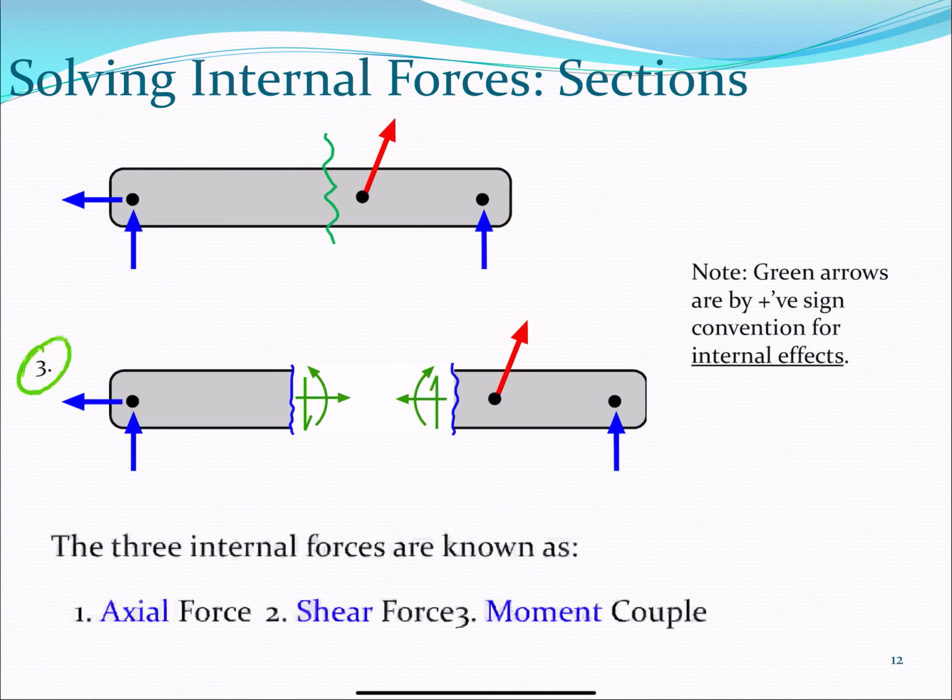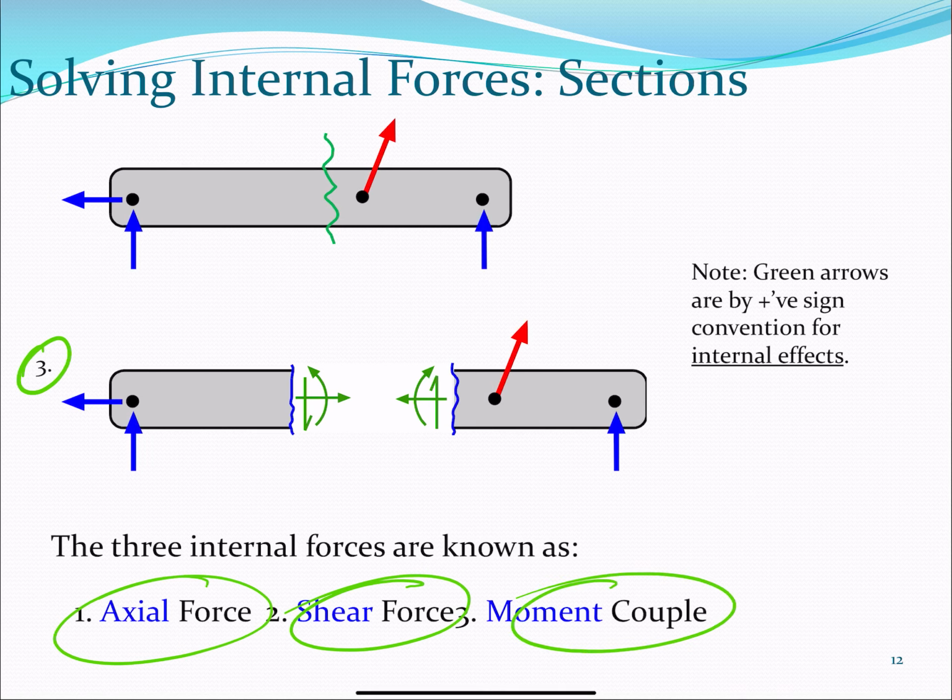There are 3 types of internal force that you have to remember, right? There is axial force, there is shear force, and there is moments, right? Now, axial force and shear force are the forces that we were using in the past. So forces we have seen and moments we have seen. So this is the point in which we realize that we have been learning about forces and moments because we were expecting the point in which we will slice a rigid body and we will find them again, right? We will find them again.